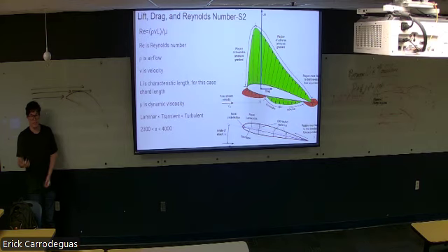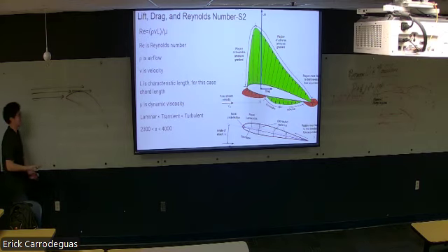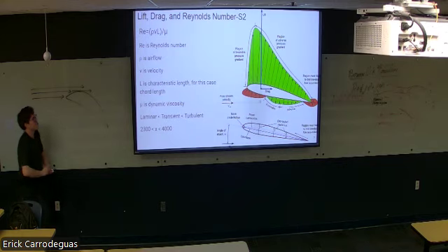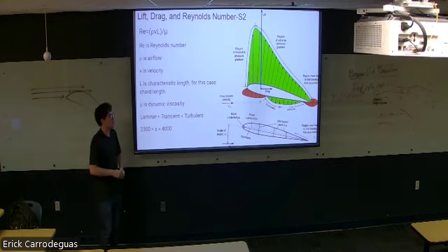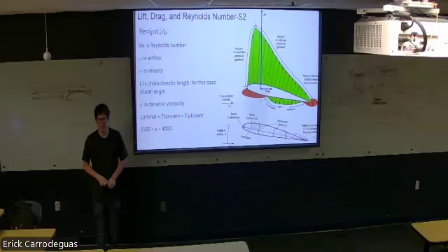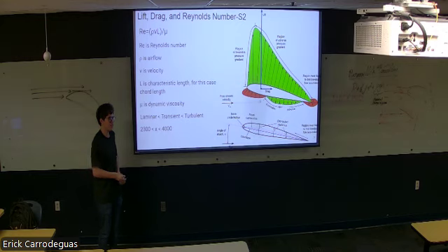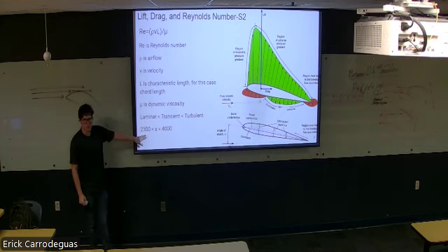And then to break a stall, it's a lot more difficult. So for our wind tunnel, there's a considerable range for the Reynolds number. When we use XFLR5, we can use any Reynolds number we want, any pressure we want, any air density we want. But our wind tunnel is much smaller. So laminar flow for a wind tunnel is any Reynolds number under 2,300.